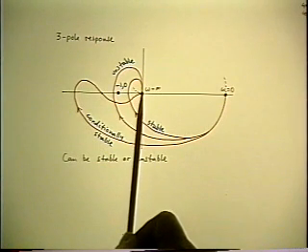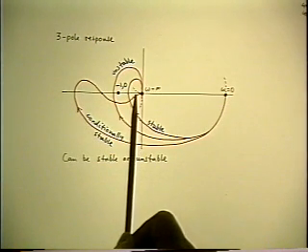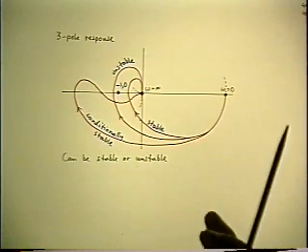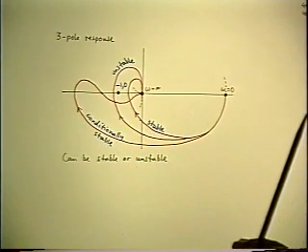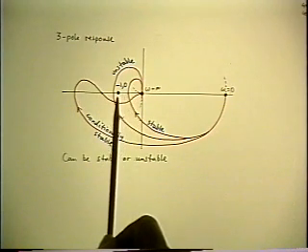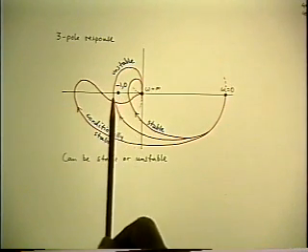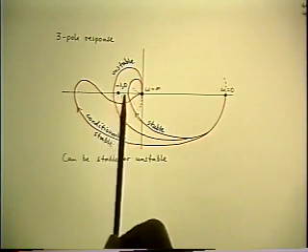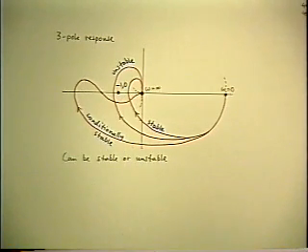And the answer now to the stability question is, well, it could be stable or not depending on the size of the contour. The smallest one is stable because it doesn't go around -1, but the next one out, which is basically the same shape, is unstable because it's bigger and it does go around the -1 point.